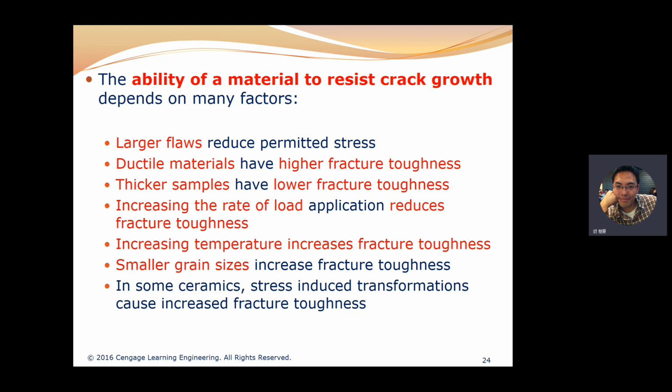That means this material may recrystallize, or its grains will regrow due to this elevated temperature, right? When the grains regrow or recrystallization occurs, that will increase its fracture toughness, such as when we anneal a material, which increases its toughness and fracture toughness. And a smaller grain size increases fracture toughness. We already mentioned a similar idea.